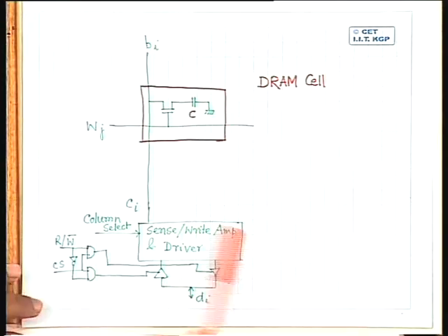Okay. So I have to have an additional facility that whenever you read any RAM cell, I should be able to refresh the RAM cell back. That means whatever value is read, the immediate next action should be you write the same value in the same RAM cell, which is called DRAM refreshing. That means after every read operation, the DRAM has to be refreshed.